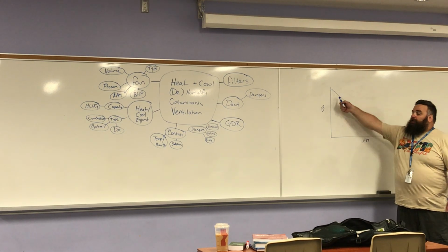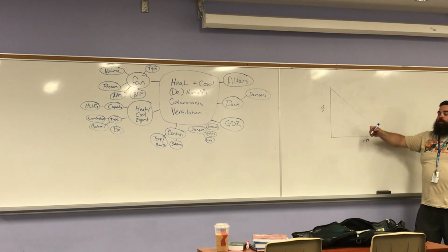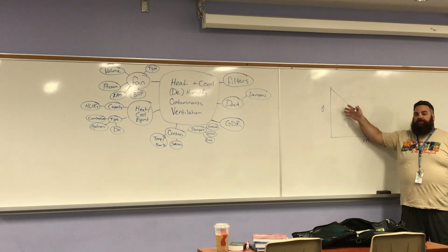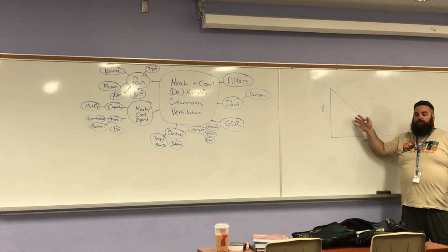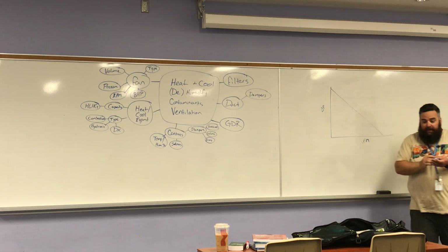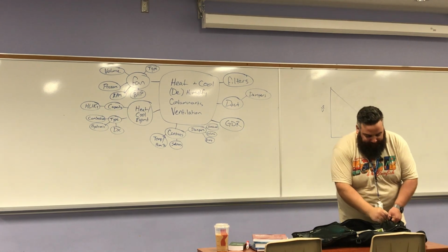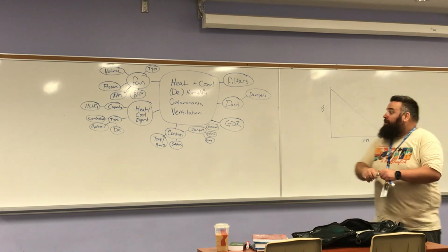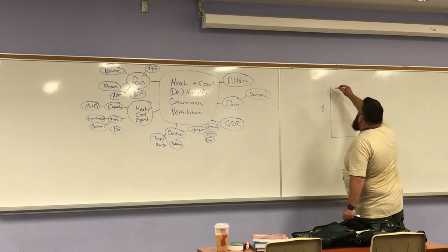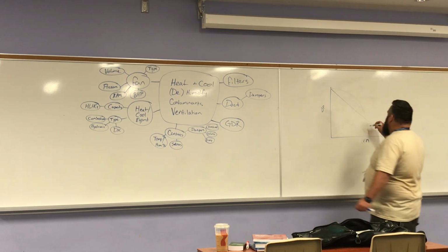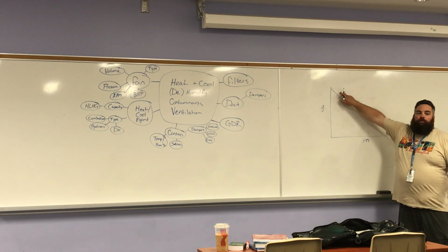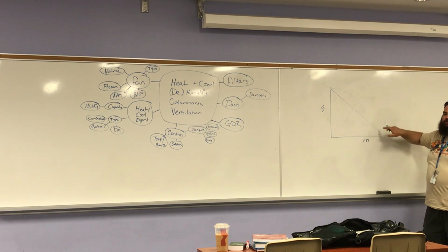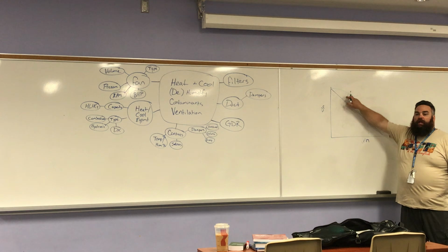It follows a very nice path where every change in pressure results in a corresponding change in flow. But a non-linear damper might look something like this, where we don't have the proportional change in CFM compared to the change in pressure.